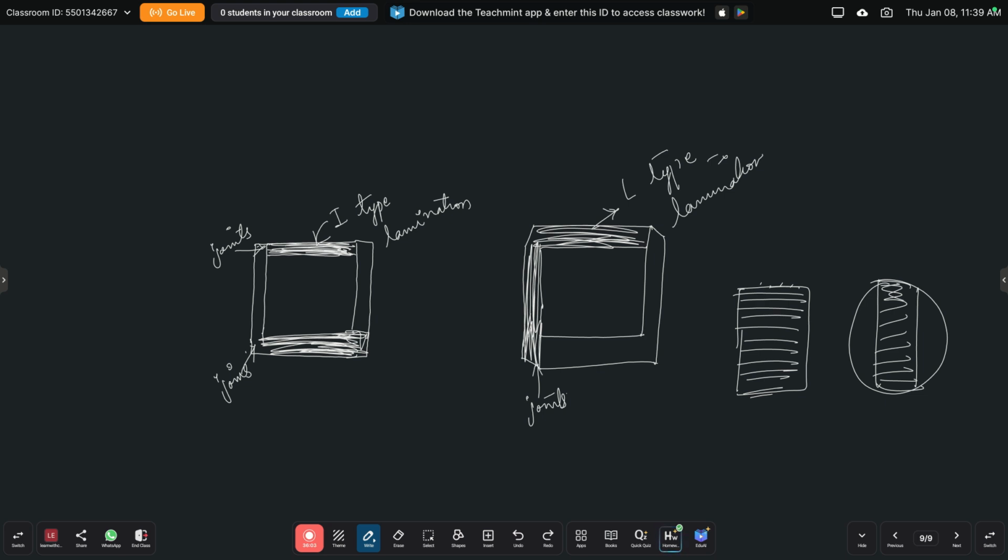So the complete laminated core consists of a number of rectangular laminations placed parallel, alternately one over the other, so that the joints are staggered. These joints are staggered to avoid a continuous gap and to improve the mechanical strength. Otherwise, we can say the joints are staggered to avoid high reluctance at the joints. The alternate layers are stacked differently to eliminate the joints. This is called staggering.